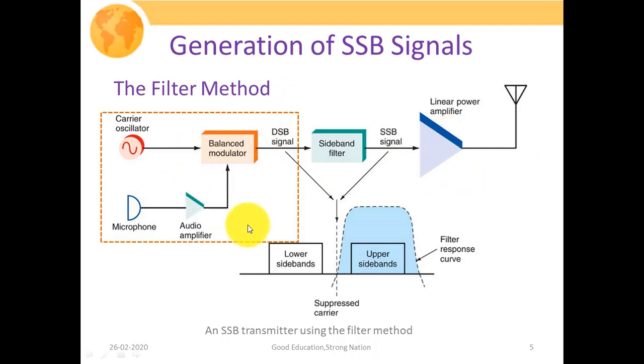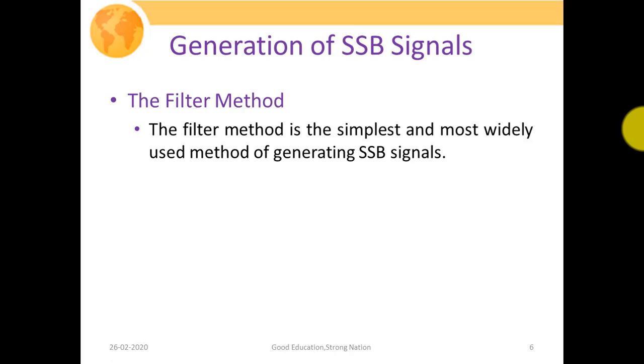If we closely observe, it is our double sideband suppressed carrier generation method that we had already studied. So now we will understand the working of the filter method in greater detail. The filter method is one of the simplest and most widely used methods for generating single sideband signals.